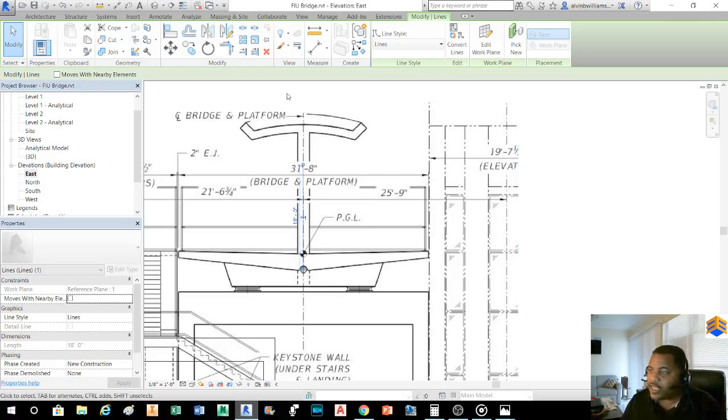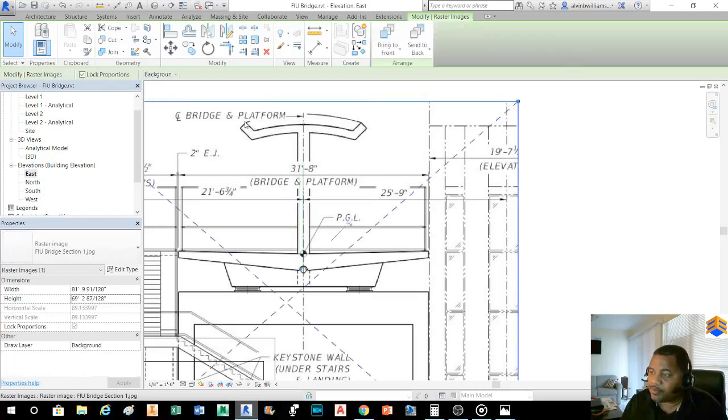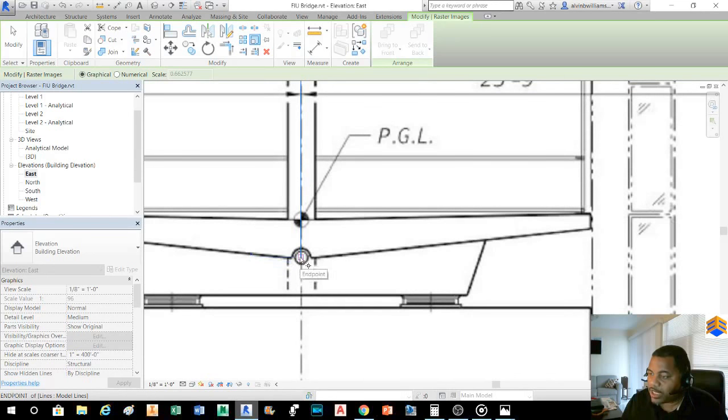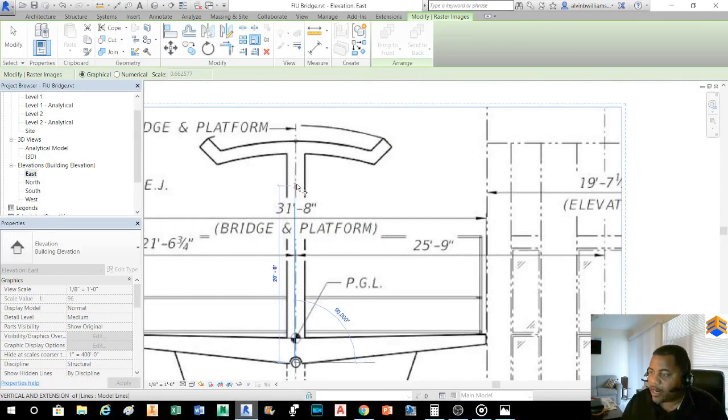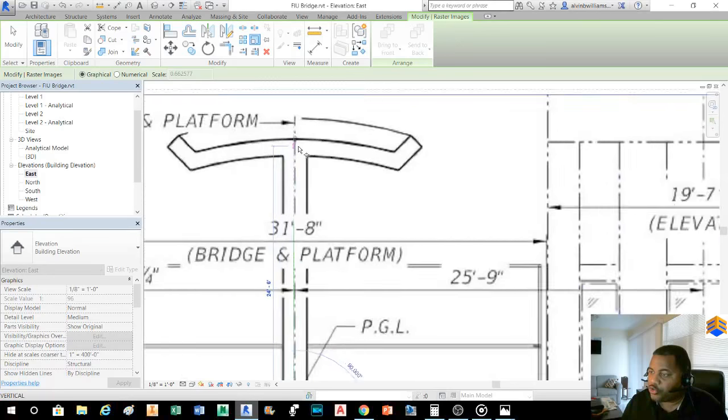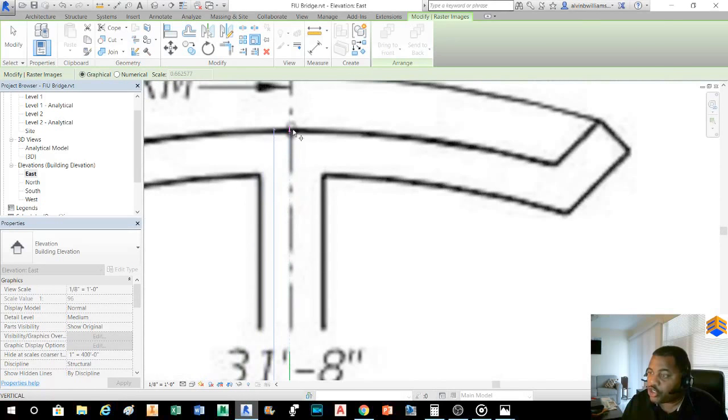So to scale the image down, I'm going to click the image. I'm going to go to my scale tool, click it, and click at that starting point where the line is and where the image starts. I'm going to click one time, and then go all the way to where the picture should be 18 feet long, but it's not. Remember, it's not 18 feet long.